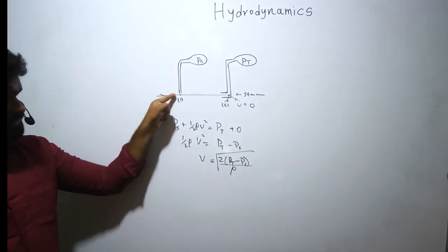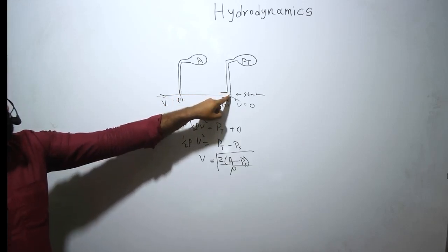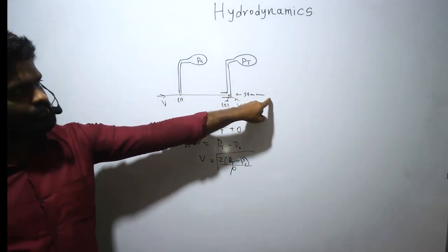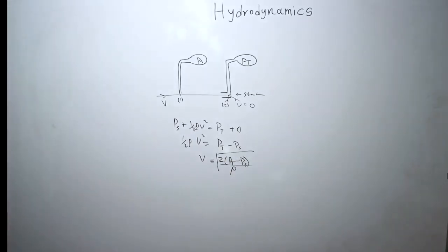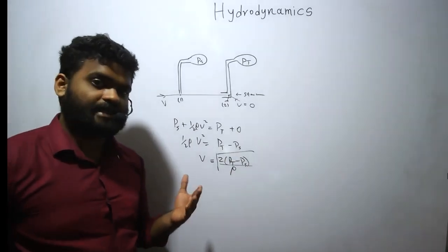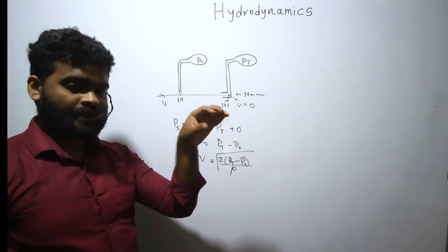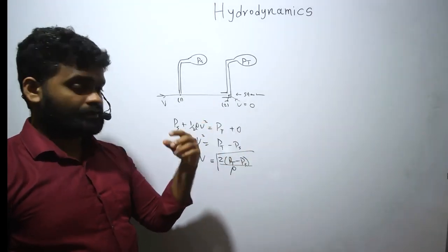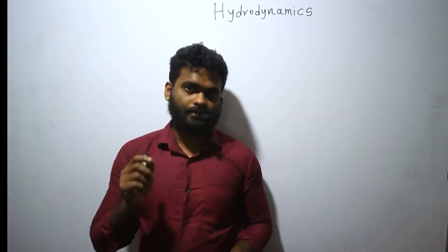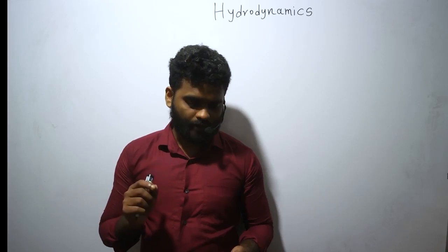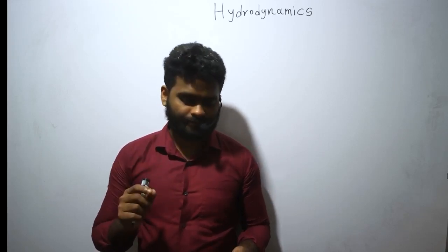So the streamlined velocity here is V, then here the velocity becomes 0, right? So such a point is called stagnating point. You have the application of that in a pitot tube, where you have to find the velocity of an air stream, right? So it is a similar application you apply. Right, 14. Water leaving from holes at A and B falls on the same place.